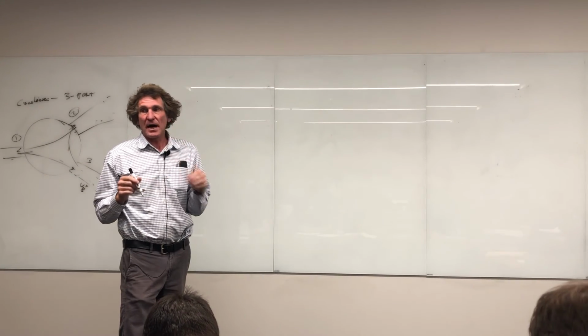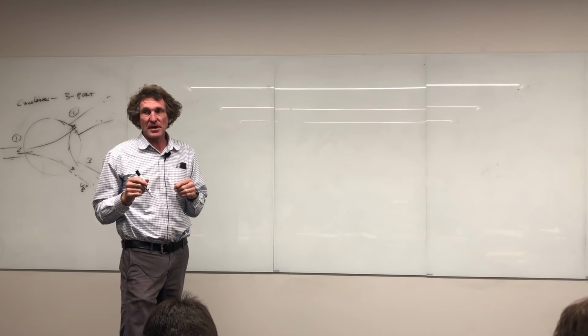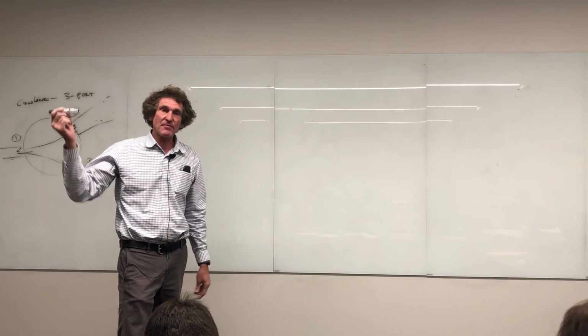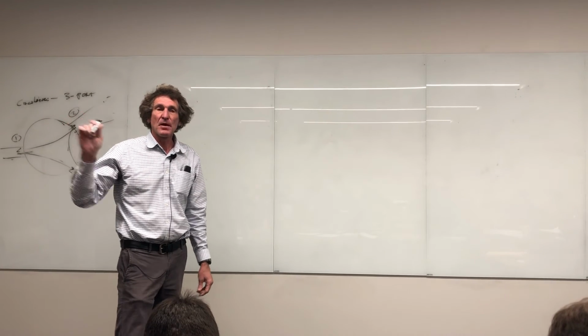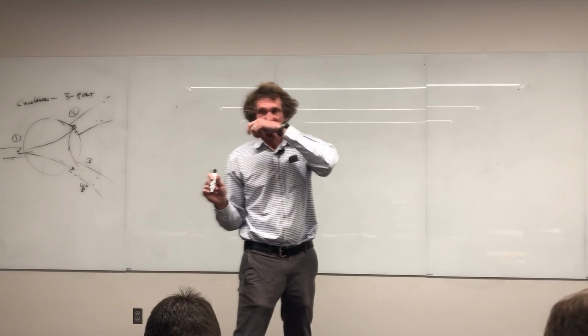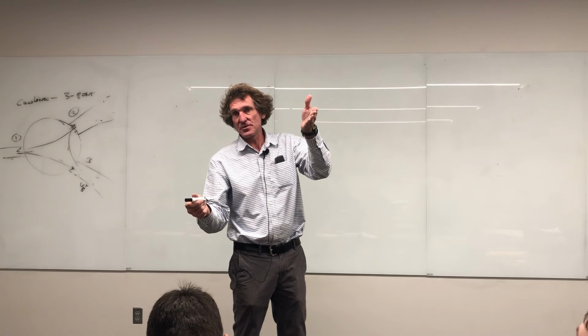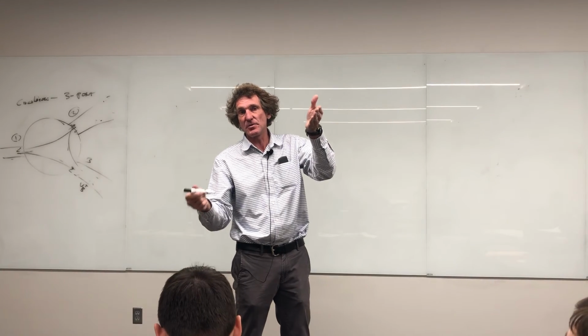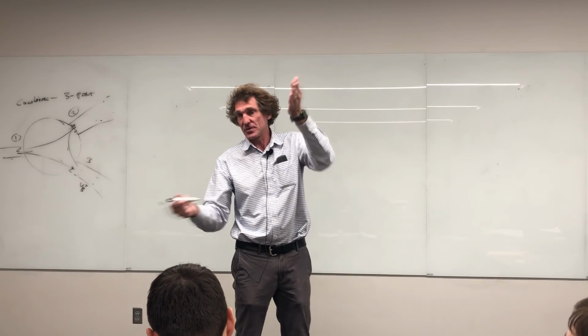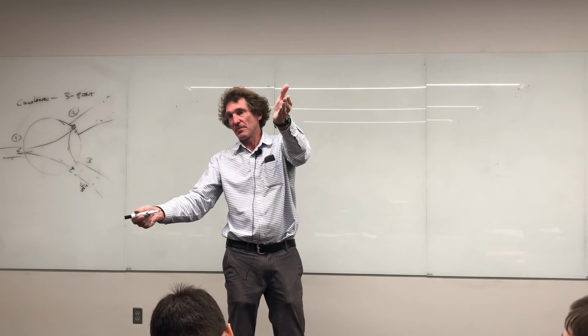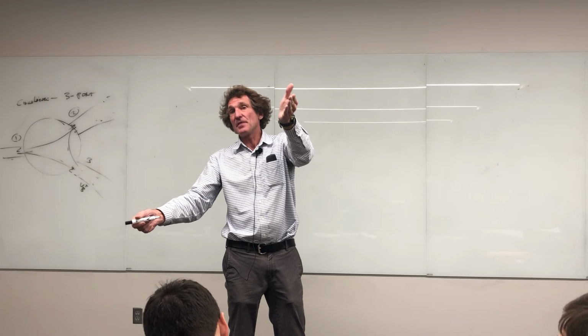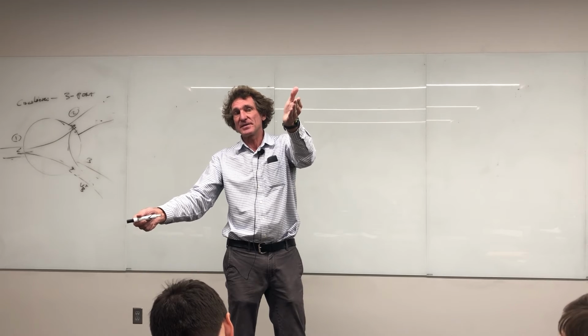But then you want some isolation on another port, but you also need a reference signal. Now let me explain something. With radar, you transmit a signal, but you need some of that signal. You're going to use some of that signal to do digital signal processing, and you'd like the signal to be synced with the exact time it was transmitted. So they peel off some of it. All right. Then there's another port, and this is the one that has the greatest isolation.